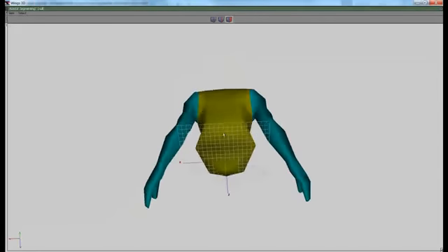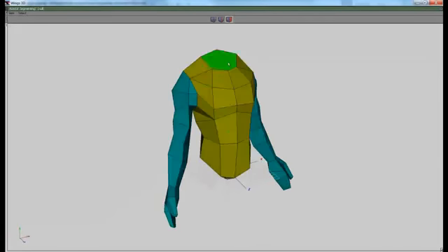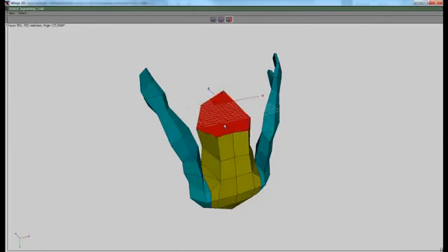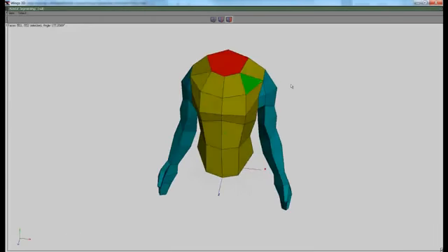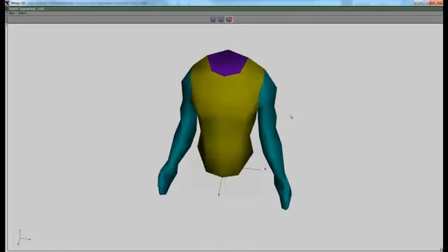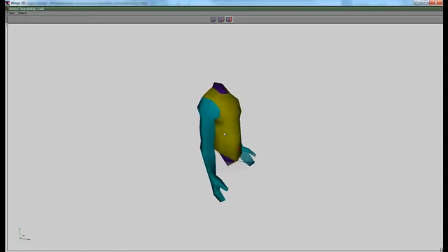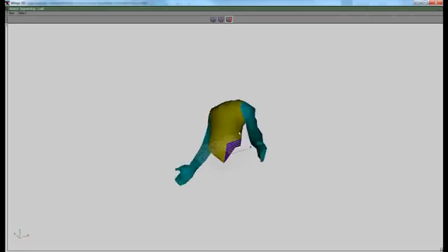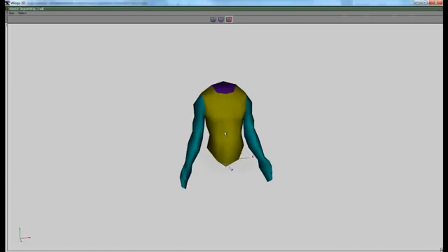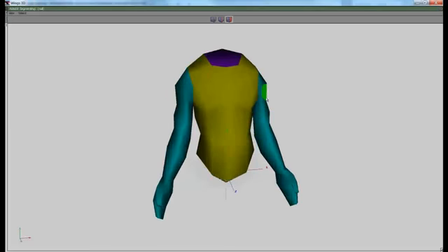Just double check that's okay. We can select the n-gons right here that we don't really want on our UV map anyway. And that's a very good simple block out of what I want my UV map charts to look like. So I want this to be one piece, and one piece.